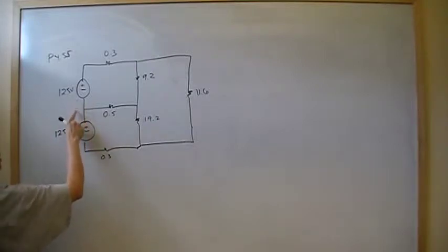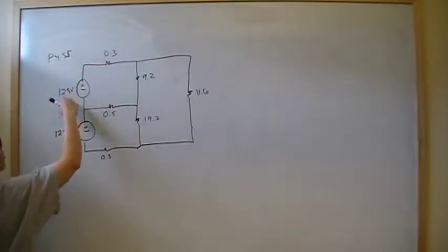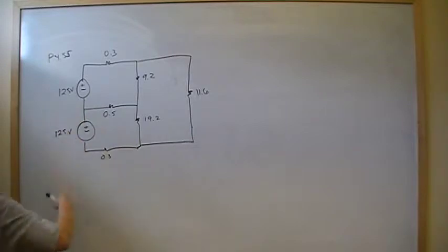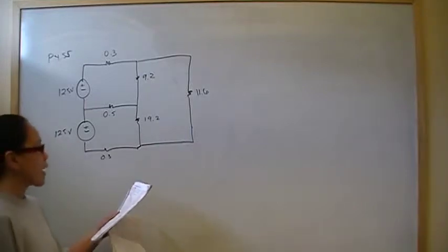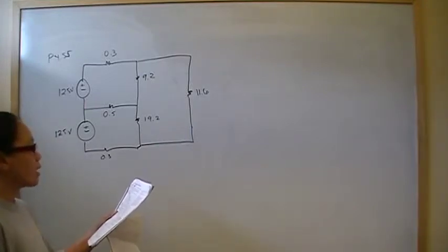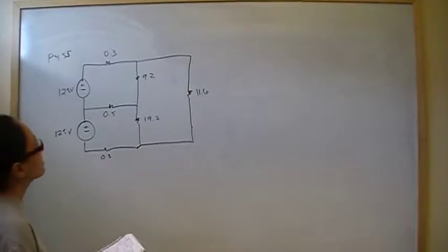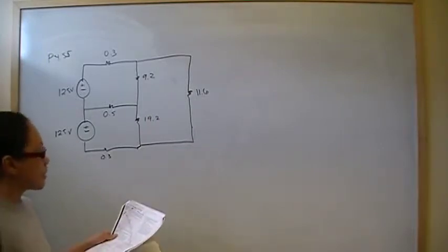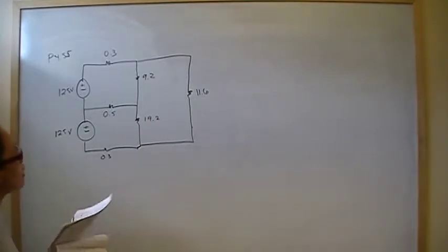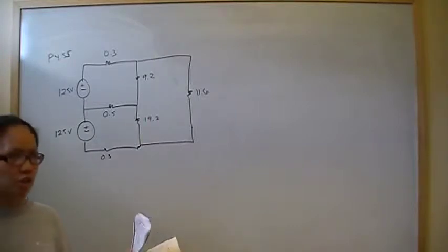From here to here, how do you write what your voltage is here and what your voltage is here? So the node voltage method is the more tricky one, in my opinion. The answer to part A is that they both have the same number of equations and unknowns. However, the mesh method is much easier because the equations are more straightforward.